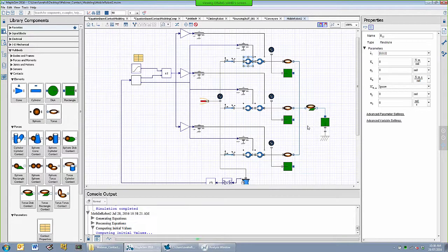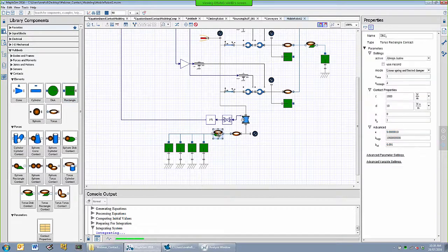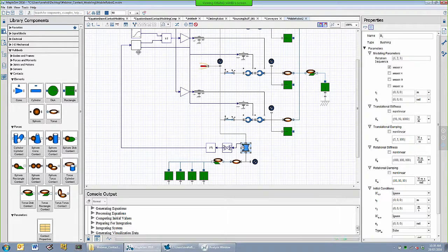I actually want to put an environment around it. So I have extra walls created using additional rectangle elements, and they all are in contact with the shield around the robot with one contact, which has one torus on one side and four rectangles on the other side. It makes creating multiple contacts, as I mentioned before, a bit more convenient. This way I can measure the force of contact and send a signal to the controller and say, you have hit a wall, please adjust course accordingly.